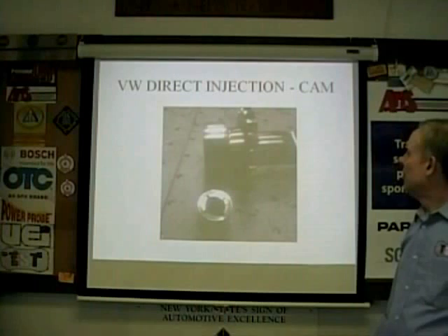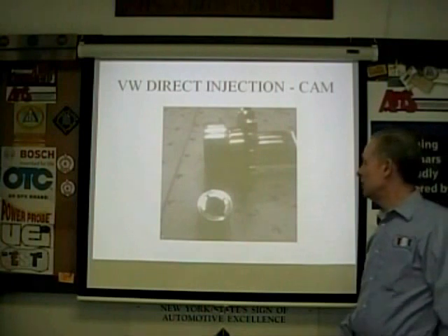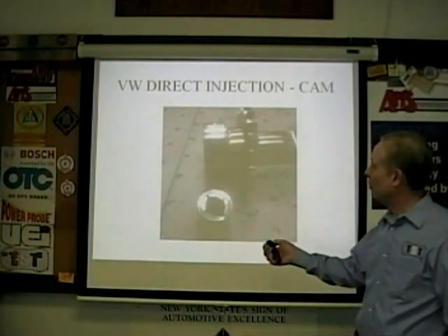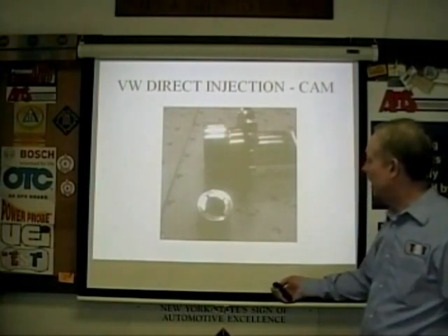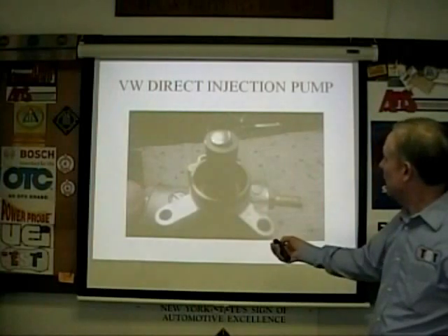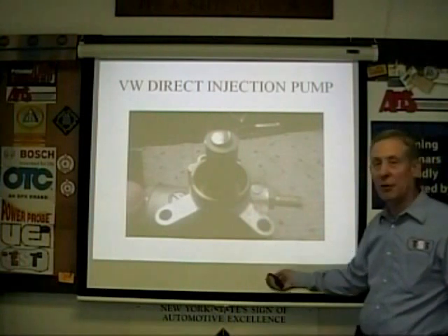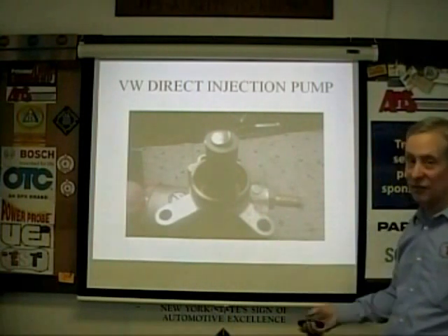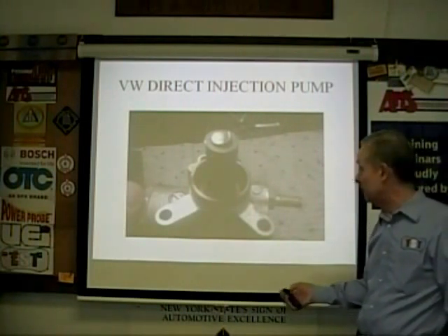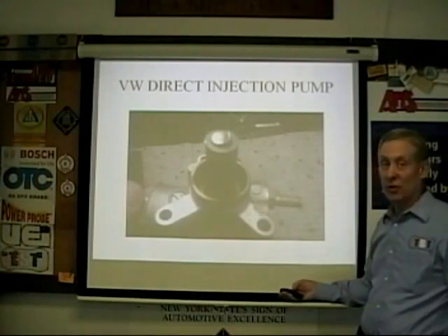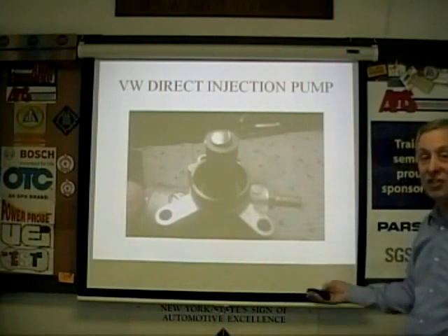All right. VW direct injection. These are high pressure pump vehicles, and this is a poor picture, but it's a cam lobe that's been ground up. This bucket here used to be solid, and it ground all the way through. This was a cylindrical shape end on the high pressure pump. This is the bottom of the high pressure pump, and it's been destroyed. It's a very expensive job. You've got to change the cam, the pump, the bucket, and rip a lot of stuff apart. All a result of having a non-VW spec, in this case non-synthetic oil in the vehicle.